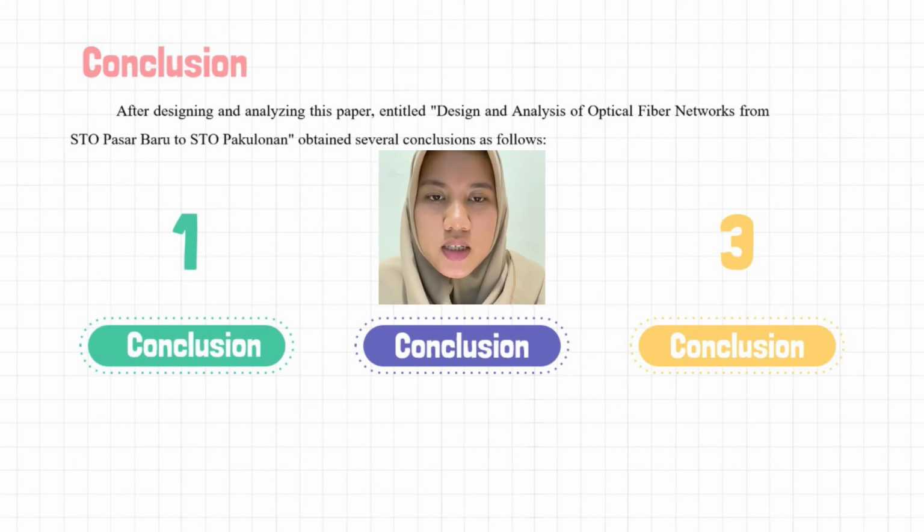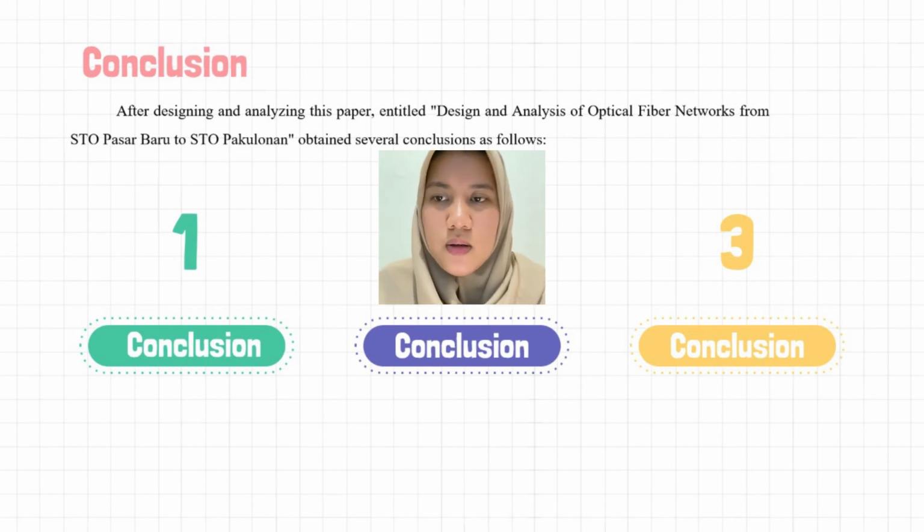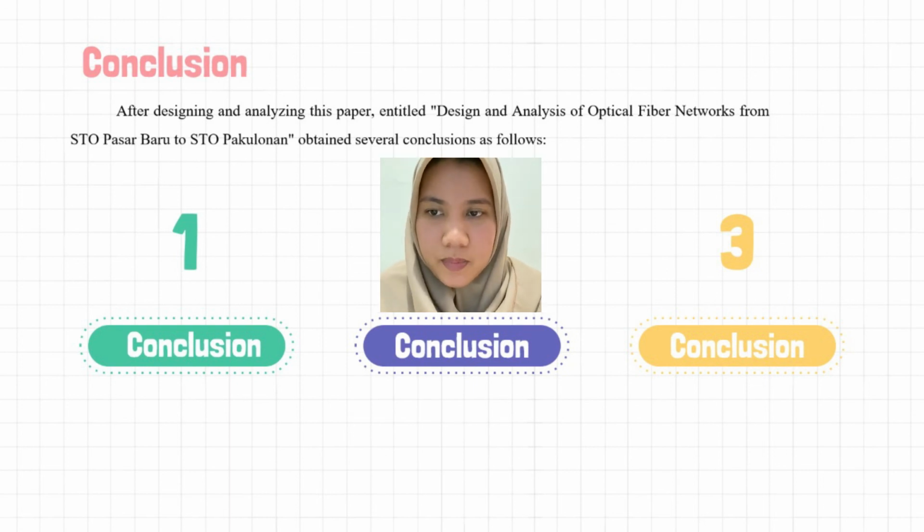In addition, the system has met the rise time requirement for RZ transmission, where 0.0990 nanosecond rise time is less than 0.28 nanosecond, 70% of the bit period, and less than 0.14 nanosecond, or 35% of the bit period.